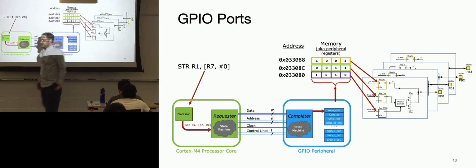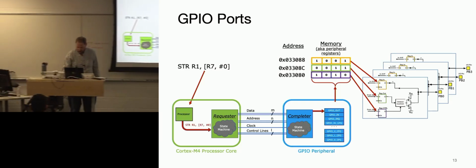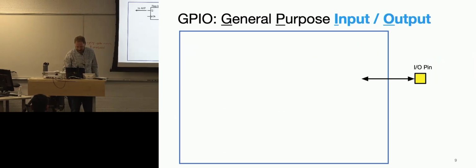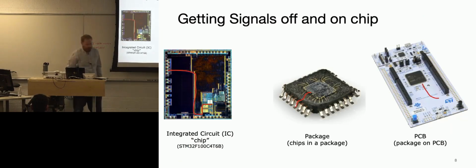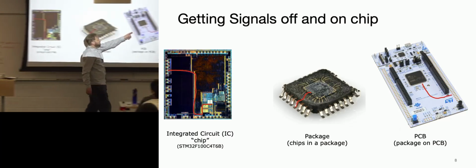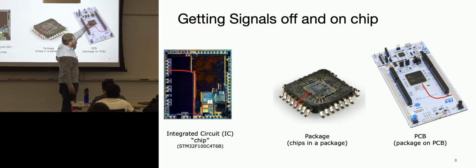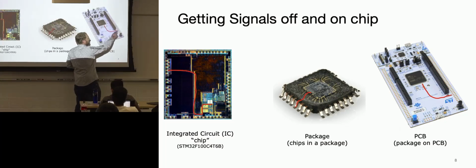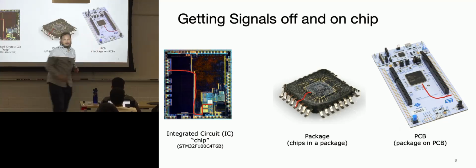Yeah. And it's always important to think about whose perspective we are talking about. So, like, if I set the GPIO pin to output, that means this pin here can drive this signal line high or low. It will drive it high. If it's an input, then it's going to sample this pin, measuring if it's high or low, and then report that into a register which can be read by the core.